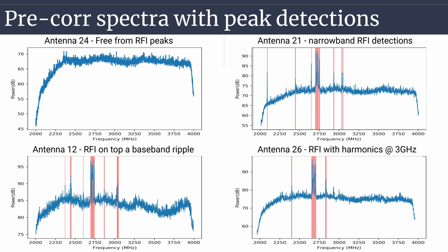One major thing to see here is that we are not time correlated between antennas. So we're doing peak finding pre-correlation and trying to flag in post-correlation, which isn't fully determined yet. So we're using the raw timestamps, and we're not using signals that have been phased up in the correlator. Without this time correction, an RFI spike may show up in a channel or two over from what we detected after correlation. So there's some work to be done for extra bookkeeping that needs to be figured out and recorded if we want to flag pre-correlation.